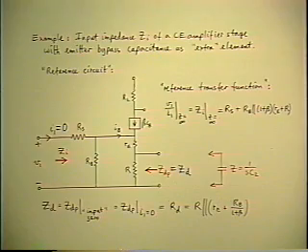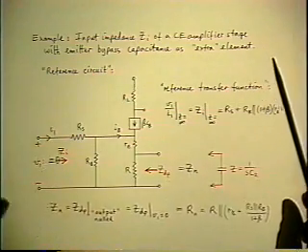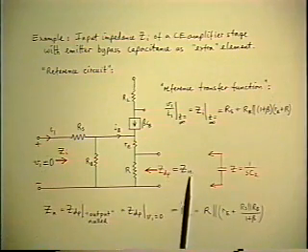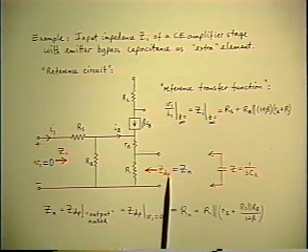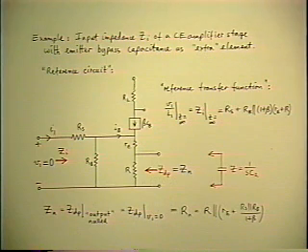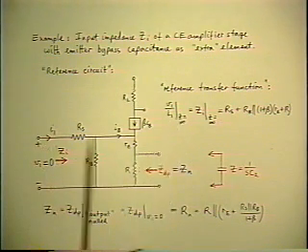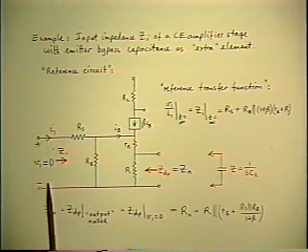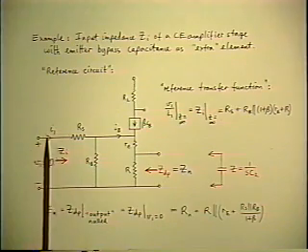The second one, again, I'm not bothering to redraw the picture. We again imagine the second source applied across these two terminals, and we're going to calculate Zn now under null double injection conditions, which means the original input is restored. The original input is I1. So there's an I1 that we imagine being put into the input terminal again.